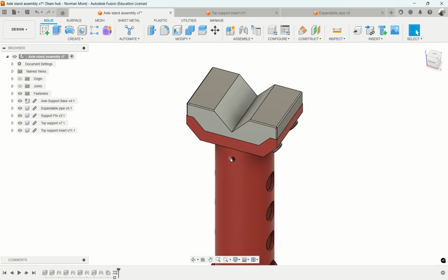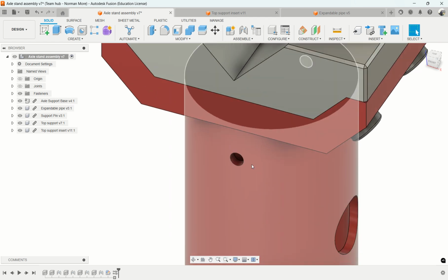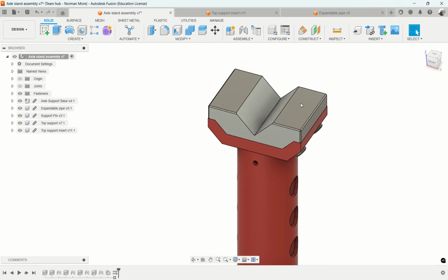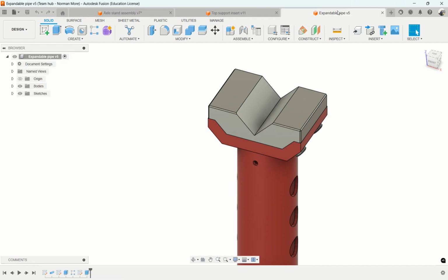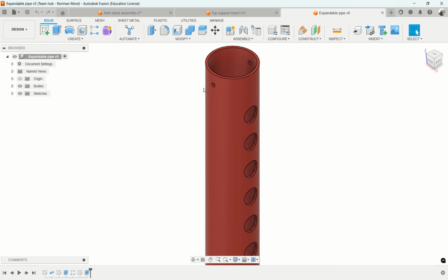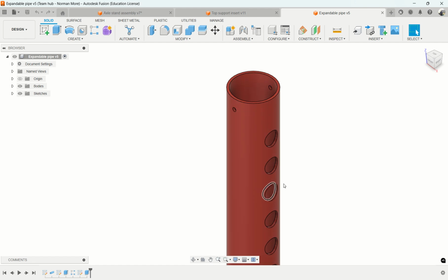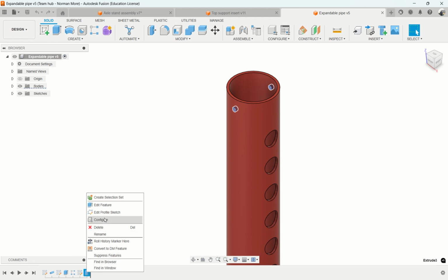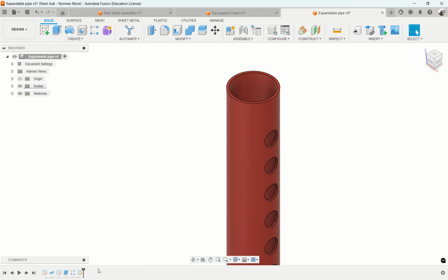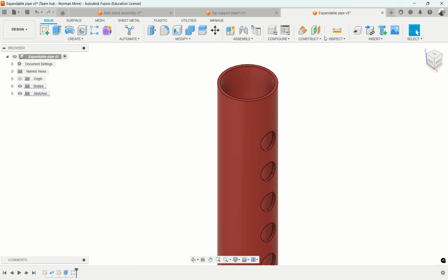Now this one, these holes have been put in a cosmetic form. So instead of doing in context like I did last time, I'm going to go to the actual part, modify it, and you see that even the assembly is modified. So just go down here and delete this hole, and the hole deleted. I don't think we need even that sketch. And then I'm going to make an offset sketch.